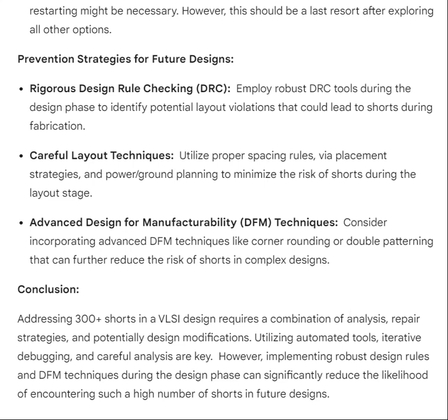Advanced design for manufacturability, DFM, techniques. Consider incorporating advanced DFM techniques like corner rounding or double patterning that can further reduce the risk of shorts in complex designs. Conclusion. Addressing 300 plus shorts in a VLSI design requires a combination of analysis, repair strategies, and potentially design modifications. Utilizing automated tools, iterative debugging, and careful analysis are key. However, implementing robust design rules and DFM techniques during the design phase can significantly reduce the likelihood of encountering such a high number of shorts in future designs.